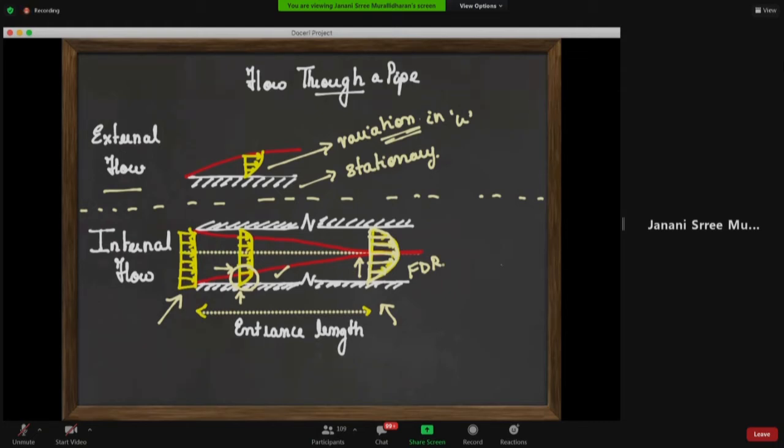Anybody wants to have a go at it? If I want to have a large amount of heat transfer, would I want to operate in the fully developed region, or would I want to operate in the entrance region? Do you vaguely remember the Nusselt number plot? So they've been answering online as entrance region.